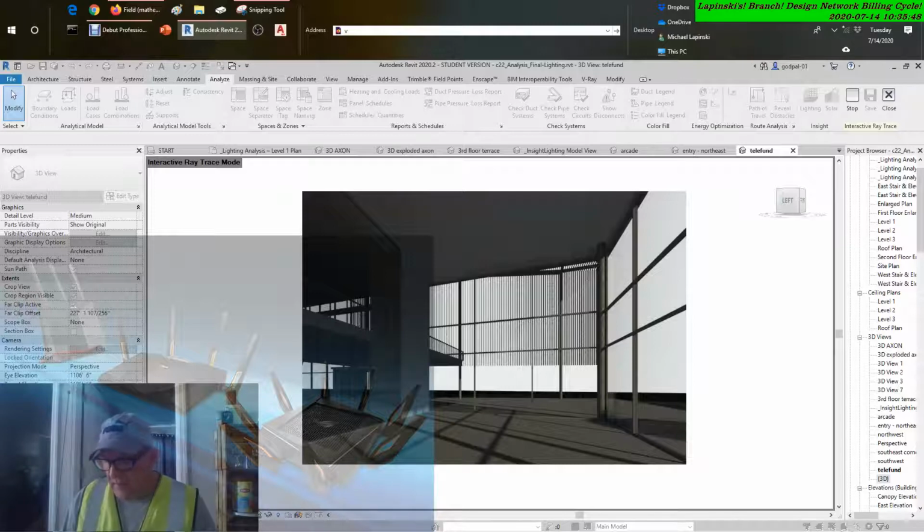Remember that this type of analysis is based on assumptions only and uses the overall size, location, and orientation of your proposed design. After you start analyzing the results, you can examine different massing configurations with the same construction systems assumptions, or varied assumptions on the same massing configuration. Running energy analysis simulations: after you have established some baseline settings and assumptions for energy analysis, it's time to create the energy model. This is the final step before running a simulation.